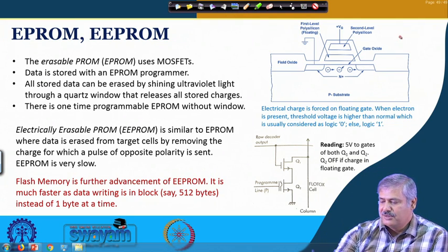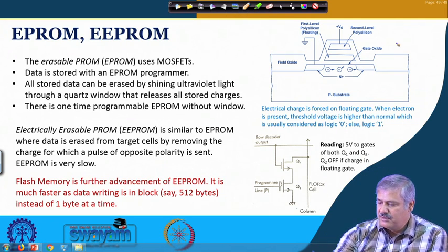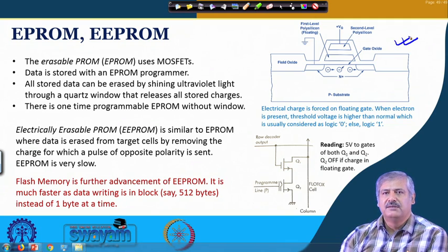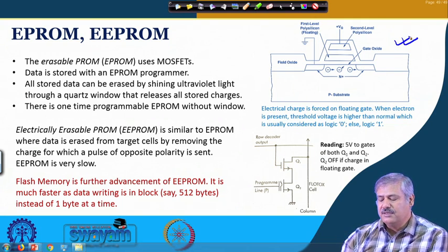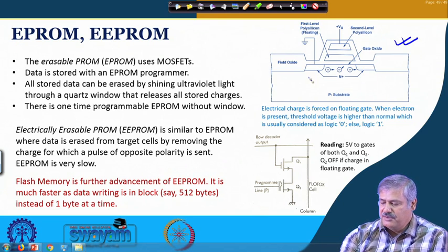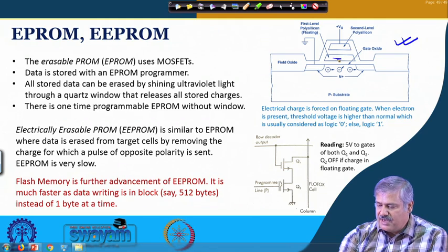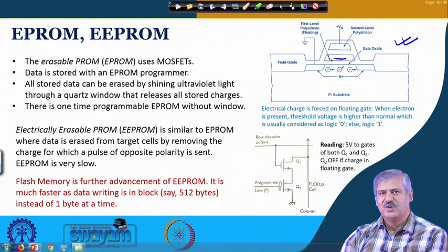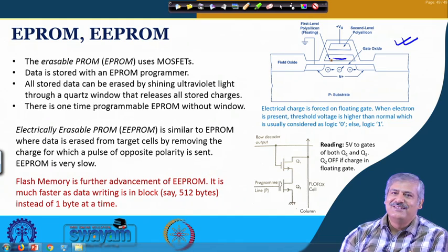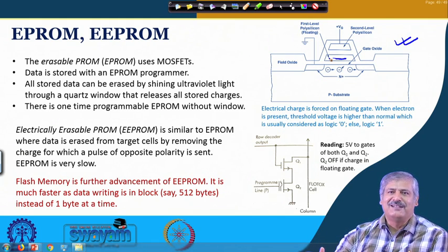Okay. So, in the MOSFET based realization of this memory cell, this is a normal standard MOSFET gate, but here there is an additional gate called the floating gate that is put over here. Okay. And by a particular phenomenon, when the appropriate physics works out, tunneling, etc., we will not go into the details of that.